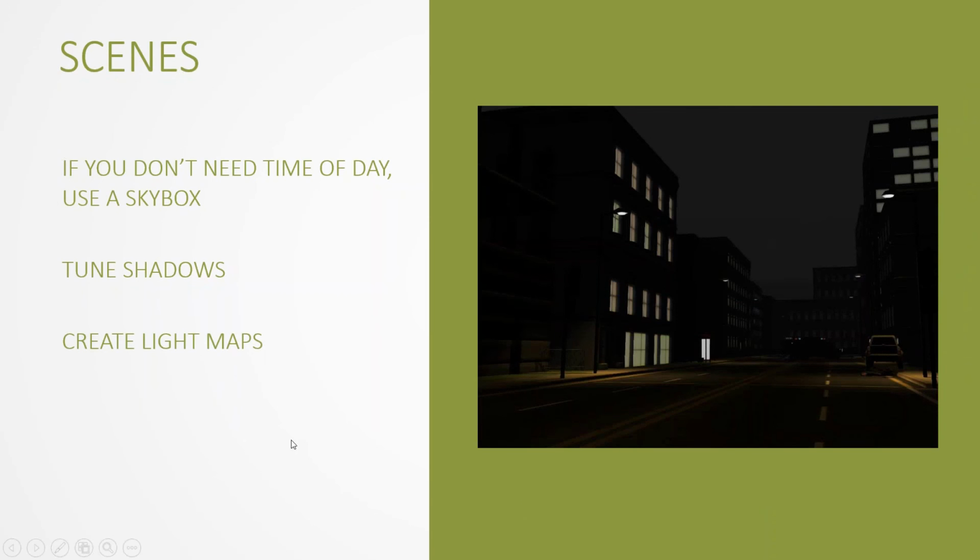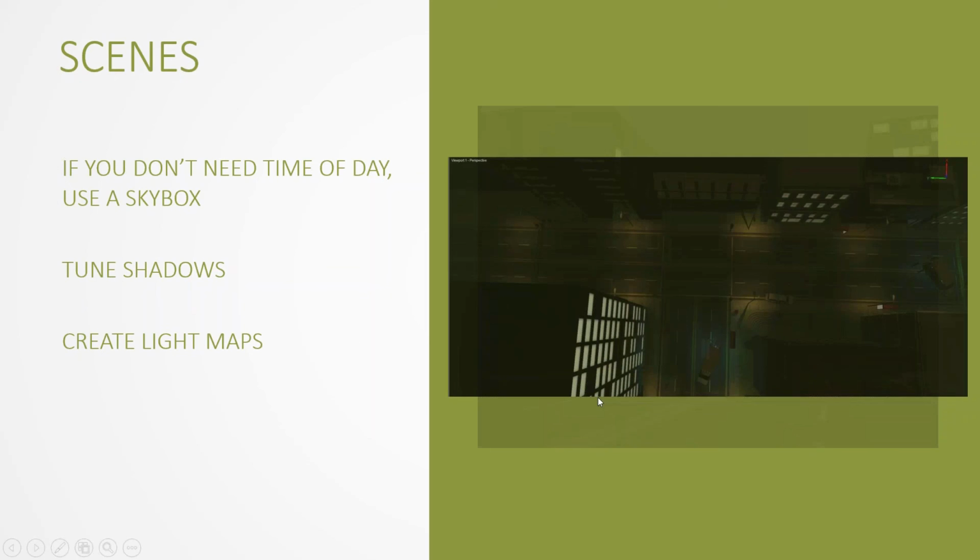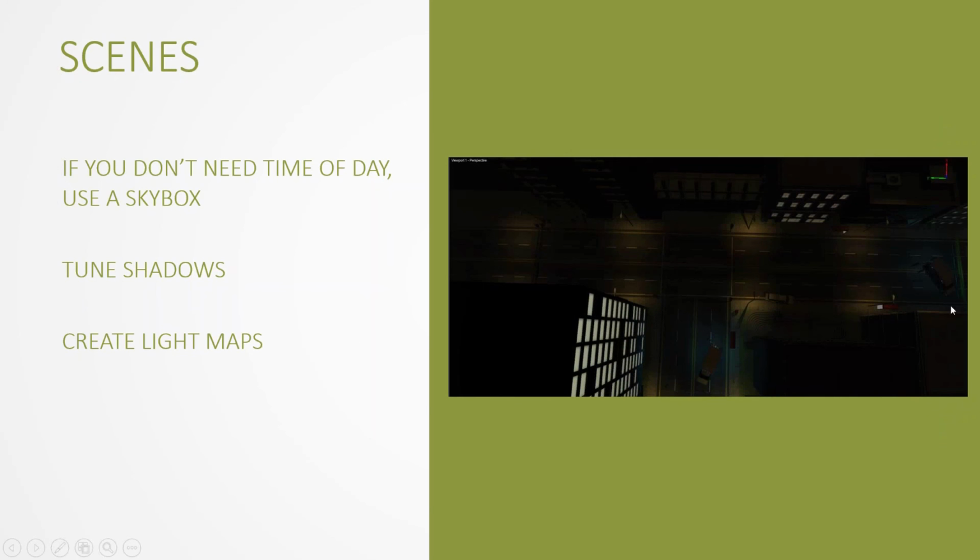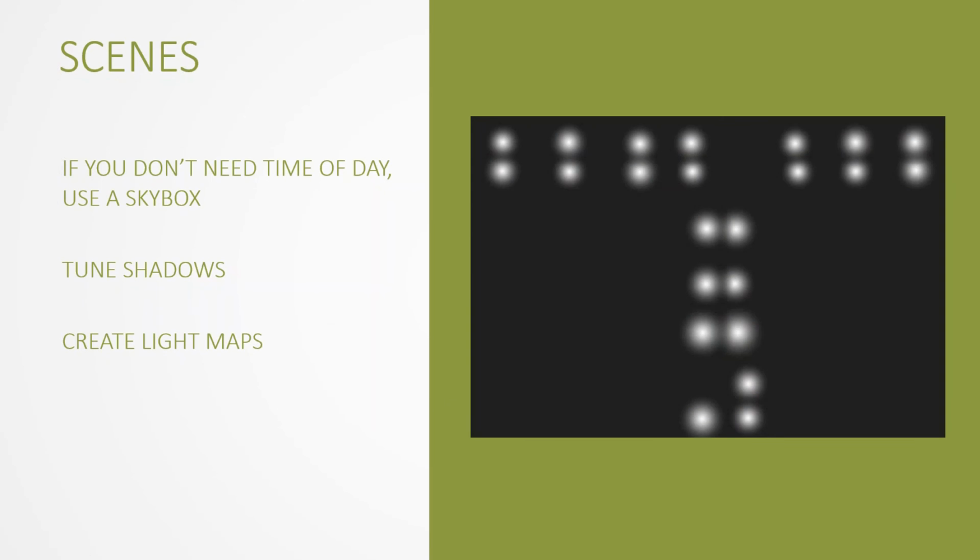The next one will be the subject of one of our case studies in a few minutes, so I'm just going to go over it real briefly, but consider using light maps in scenes with a lot of lights. And you can see here our EOD scene, which has a lot of lampposts. And if you look up from the top, you can see that there's actually quite a lot of lights. Now, in a few minutes, Marc-Alexandre will show us exactly what the performance impact of this is. But what we did to simplify it is use a texture that defines light points. So we'll look exactly at how to set this up in a few minutes, but this is one that has a very important impact on performance.